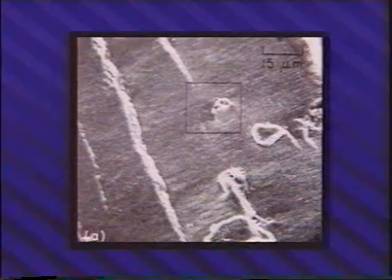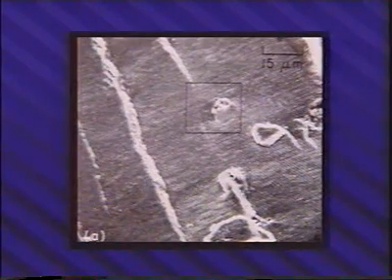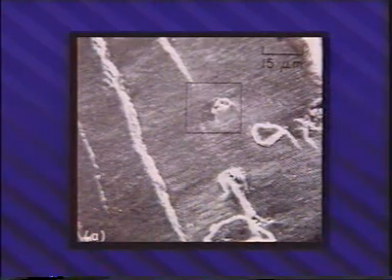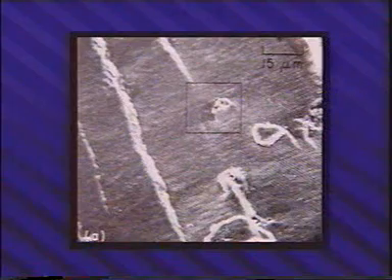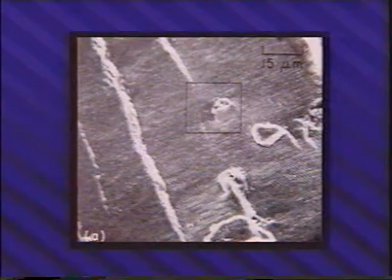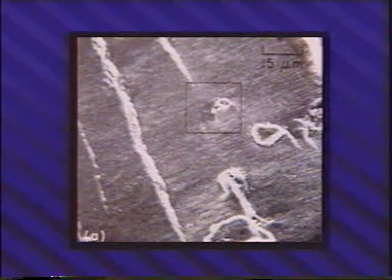Electron microscope examination of undamaged fatigue fracture surfaces in materials up to about HRC 50 frequently shows finely spaced parallel ridges or striations. These fatigue striations are oriented perpendicular to the microscopic direction of crack propagation. With uniform loading, the spacing generally increases as the striations progress from the origin of fatigue.